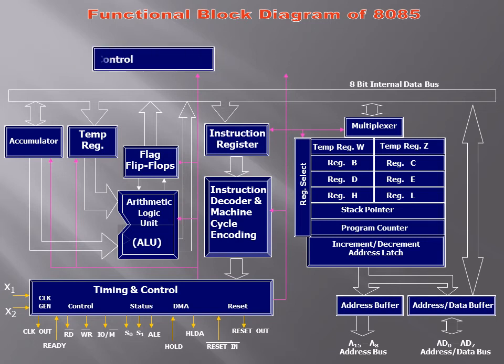And then we have the important section called the interrupt control. The microprocessor generates interrupts and it actually serves interrupts. The interrupts come from the outside devices, and they interrupt the operation of the microprocessor, and there are various interrupts. Those interrupts are signals from the outside device. So the lowest priority interrupt is INTR, and it is acknowledged by a signal called INTA.